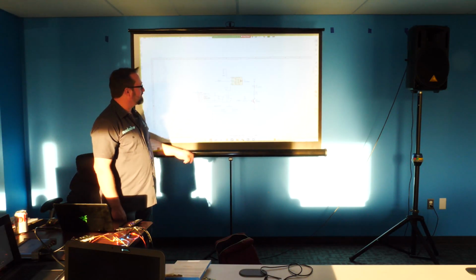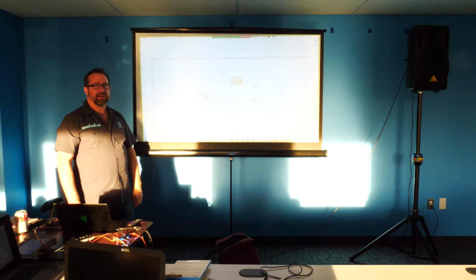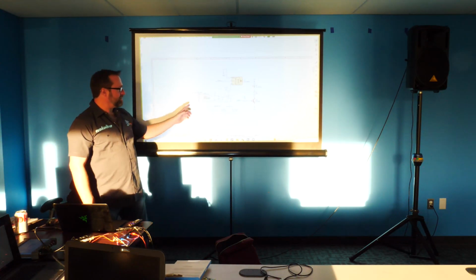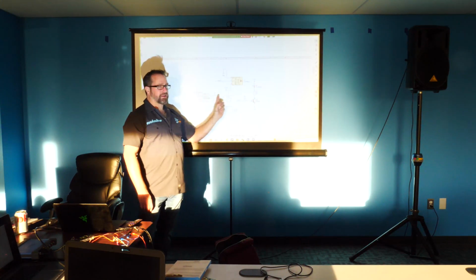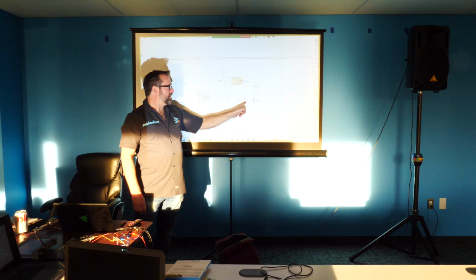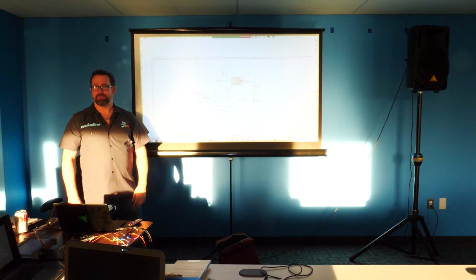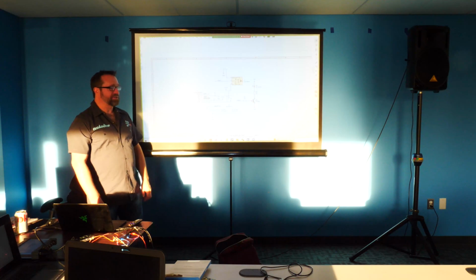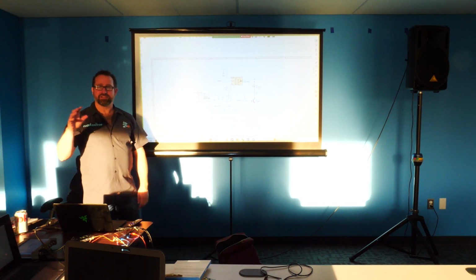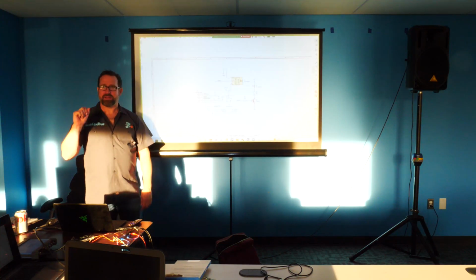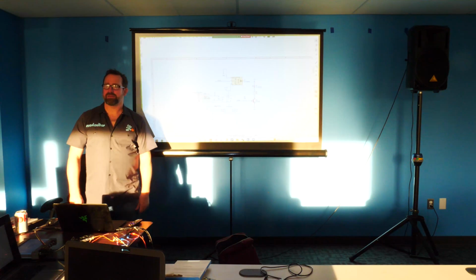Finally, there's this awesome chip here that decodes the IR. So what you're going to learn is that we actually generate a modulated square wave, which you'll see on the oscilloscope, and it's at 38 kilohertz, if I remember. But it's a very fast modulated signal, and it's amplitude modulated, so it's turned on and off. It's very common with wireless protocols.